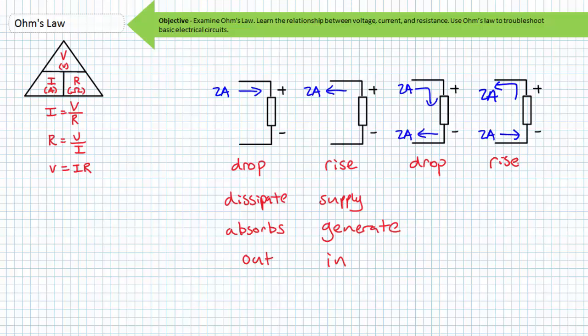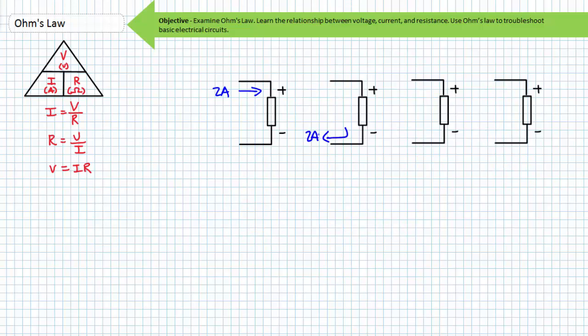This last scenario is a little tricky simply because of the negative sign. If you've got a magnitude with a negative sign in front of it and an indicated direction, all it means is that that same positive magnitude is traveling in the other direction. This is a little confusing, but what I'll draw is 4 more examples, all indicating the same quantity. If 2 amps enters our positive terminal, it also means 2 amps leaves our negative terminal. I could also say that negative 2 amps is leaving my positive terminal, or that negative 2 amps is entering my negative terminal. All 4 scenarios are saying the same thing.